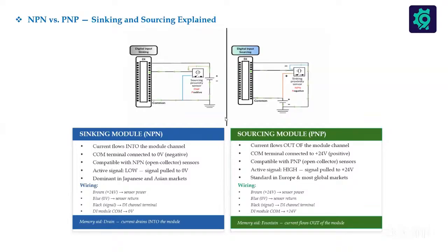Okay, it is sourcing, while the PLC is sinking. Sourcing is where the positive signal is coming from. That is the direction of flow.